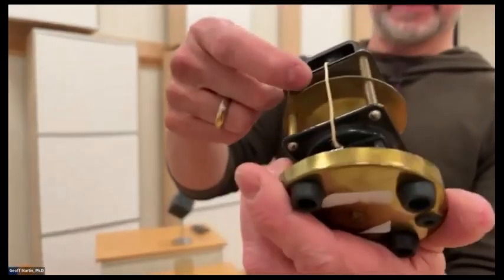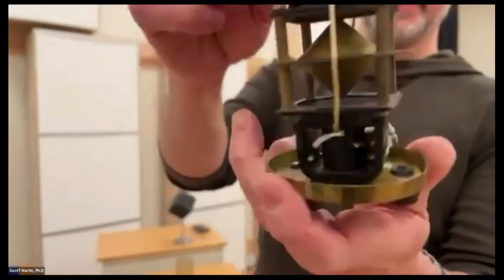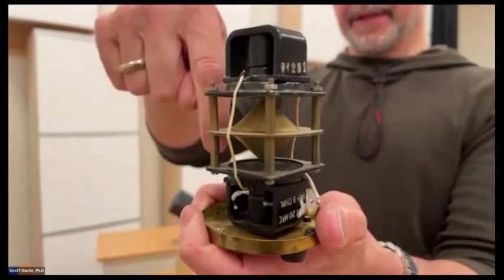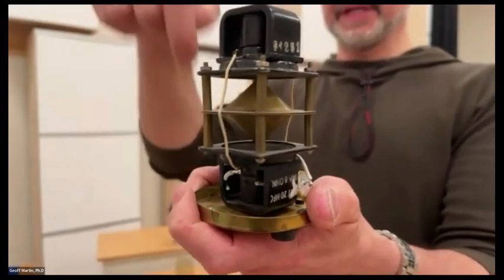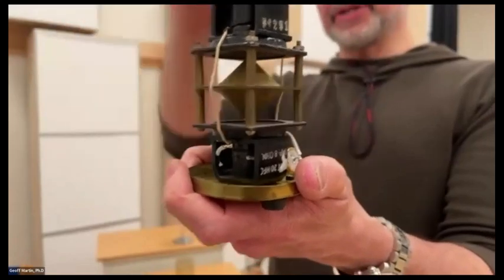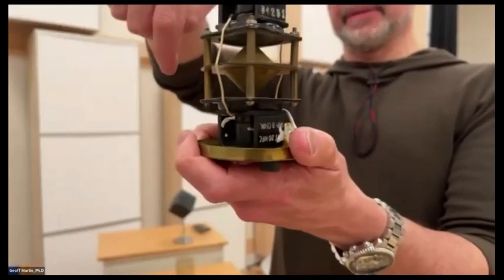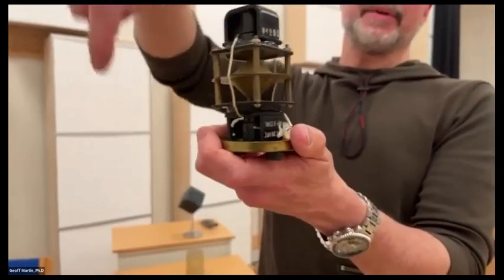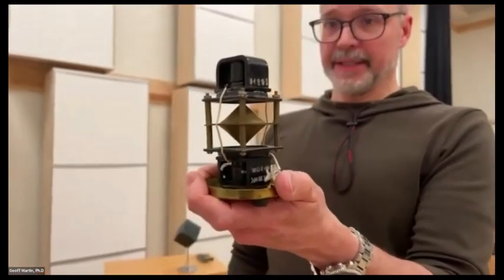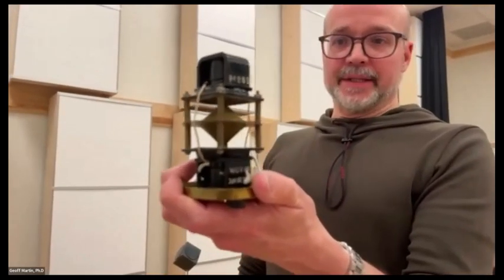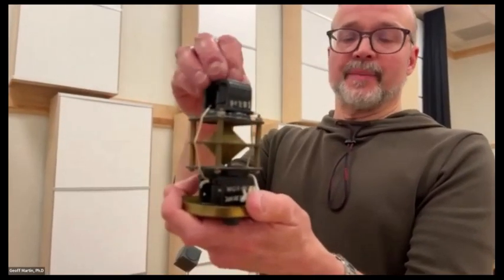We can see there's a tweeter here and another one here, and those are aimed at reflectors. So the idea being that although the tweeters were aimed vertically, this, in theory, would radiate the reflection out in a three-dimensional world, basically as a 360-degree radiation in the horizontal plane, making it more like an omnidirectional tweeter to give us a better power response.